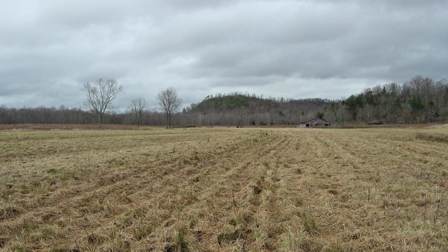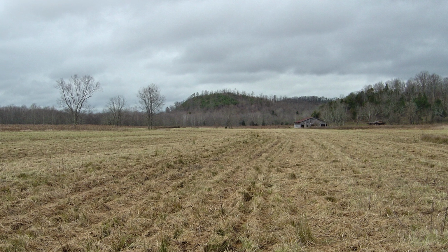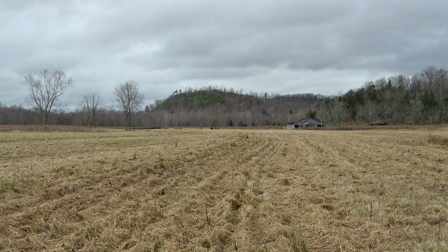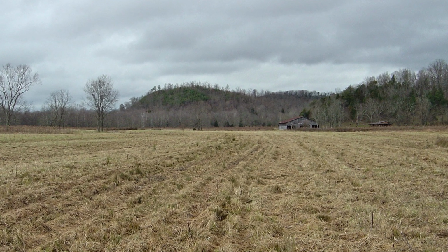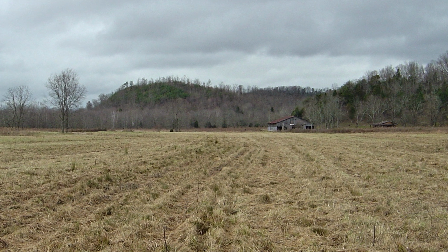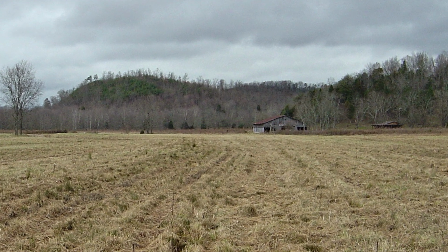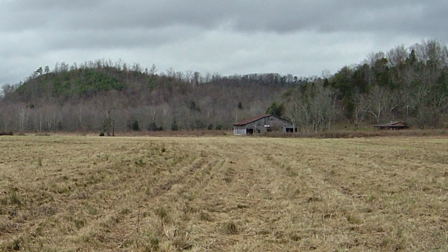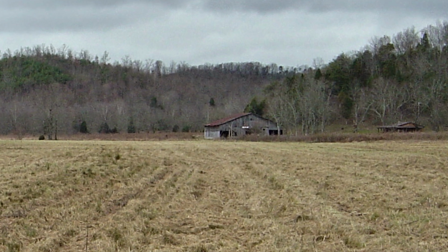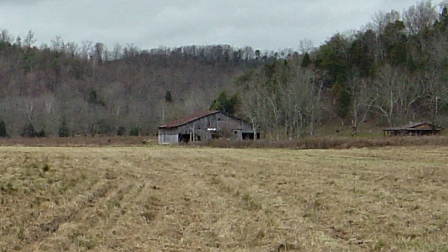A main concern of the project was not to flood the home and the barn that you can see near the base of the hill. It was determined that building an above-ground dam could flood the home, so we made sure that the elevation of the groundwater dam was kept lower than the elevation of the neighboring private land where the home was located.